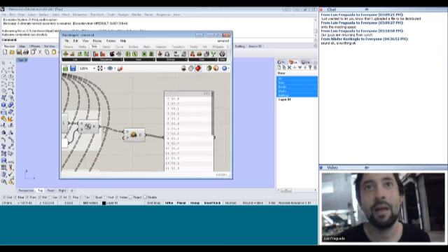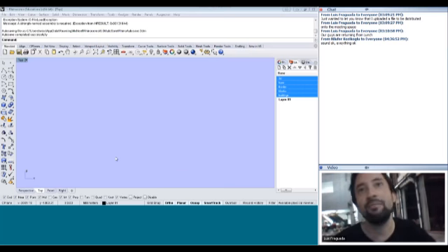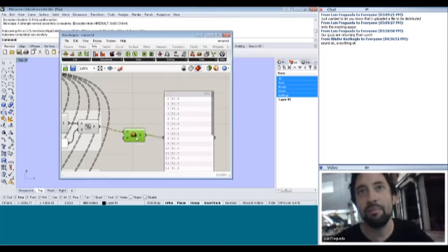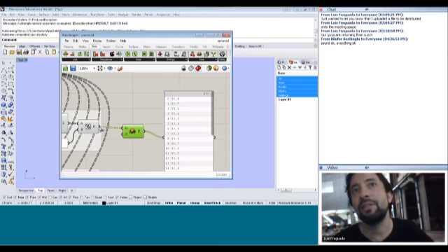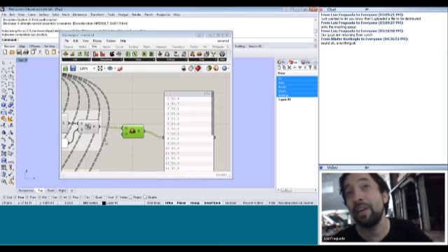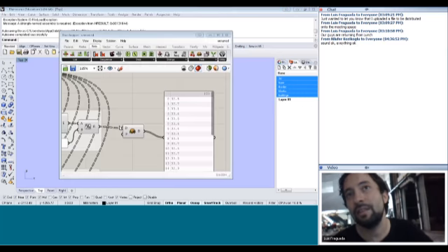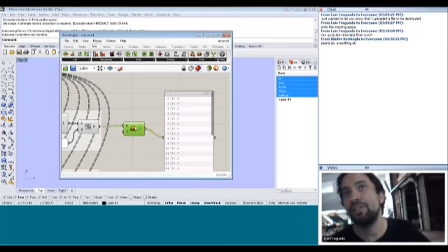By the way, on any of the inputs or outputs, we could right-click and say flatten instead of having this other component. Sorry, I don't know why my Grasshopper is lagging on me, but you can say flatten. I'm right-clicking on R, and I get this little menu. If I say flatten, it'll do the same as this whole component. I do that so I introduce the topic to you, but just for you to know further that in all of the inputs you have the option to do the same.